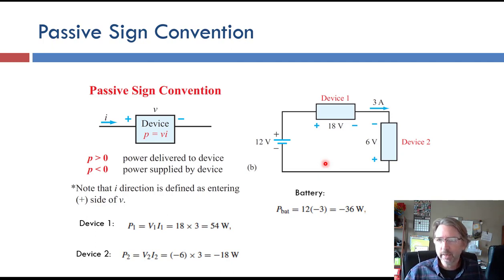There's a sign convention that comes up from time to time here in circuits. We have to decide what does positive power mean, and it's an arbitrary choice. But the convention is that positive power means it's delivered to the device. So if we have an element here with a positive voltage on this side compared to this side, and current flowing in the positive terminal, that's positive power. And this is the arrangement. For example, if this was a resistor, this is the way current would flow with the voltage on the resistor, looking like this. Resistors absorb power and get hot, and so that's positive power.